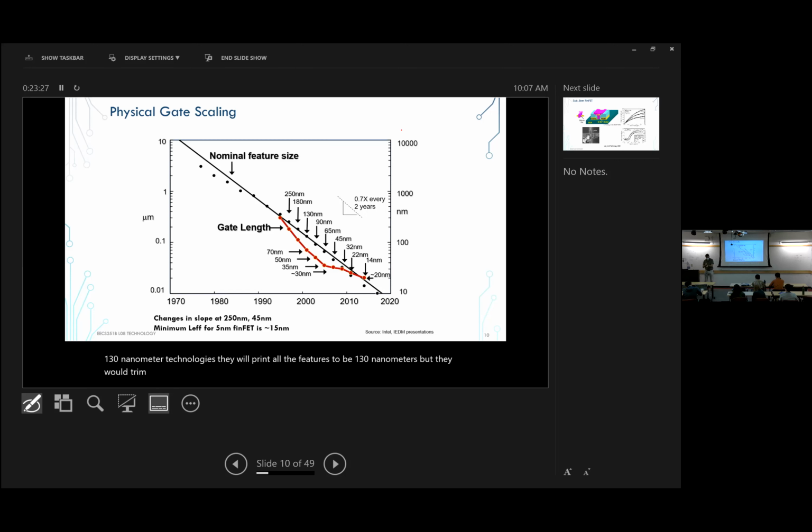They would basically sand it down to about 70 nanometers. The reason was to get more on-current, because we needed more on-current to keep the main technology driver at that time, the desktop processor, going up in frequency and increasing performance.